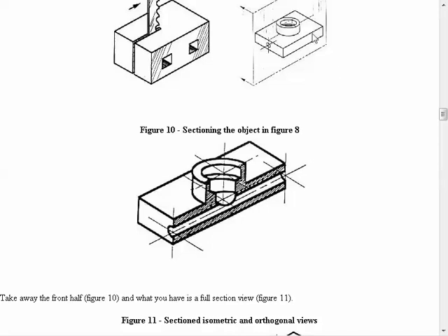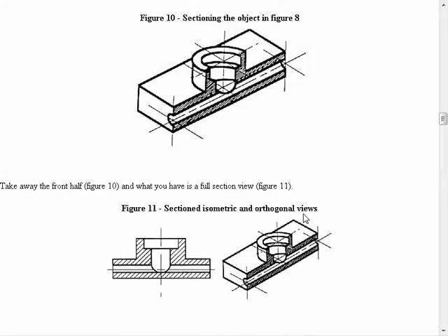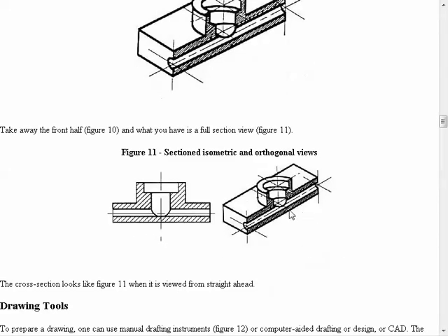We couldn't tell that from this picture. What we also learn is that there's some interesting detail going on inside of this hole that we really couldn't see well in this picture. And if we were to rotate this so that we see this side right here square on, we'd get even more detail out of it. And so we've now done that. We've rotated it so we see the thing square on, and then we can see some additional geometry information of what's going on in this hole. This is called a section view.